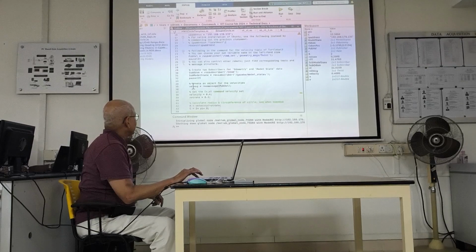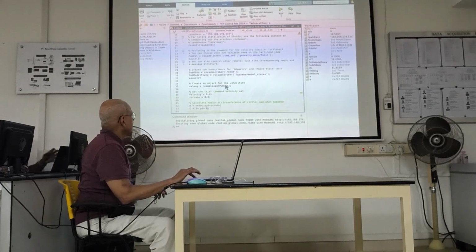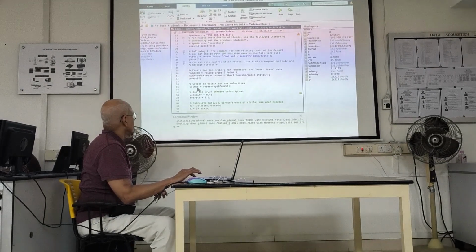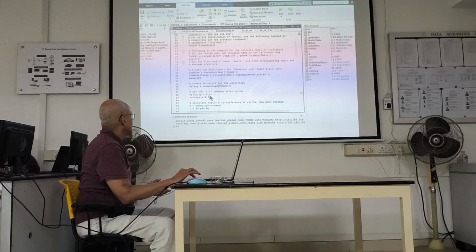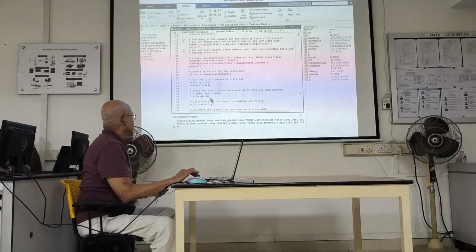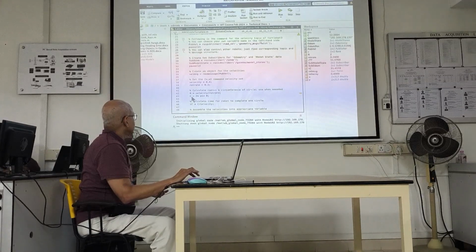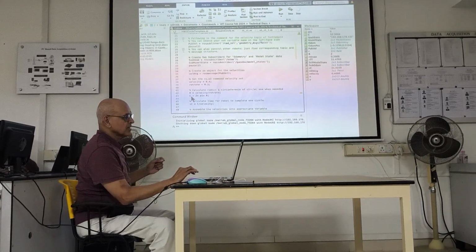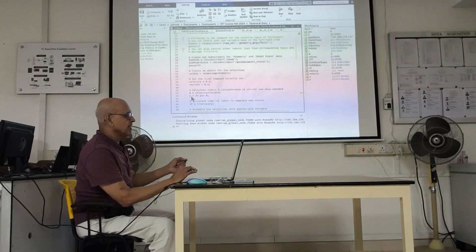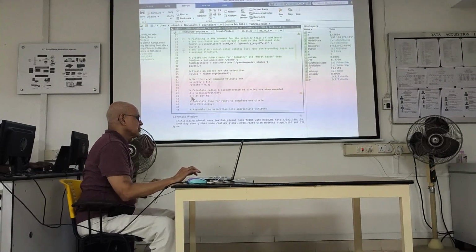So then I get an instance of the object, and this is what I'm going to load up with the velocity values. So velocity is 0.4, rotation rate is 0.2, divide one by the other, you get a radius of 2 meters. I then calculate the circumference because I'm going to use distance of travel to stop the robot after it does one full circle.